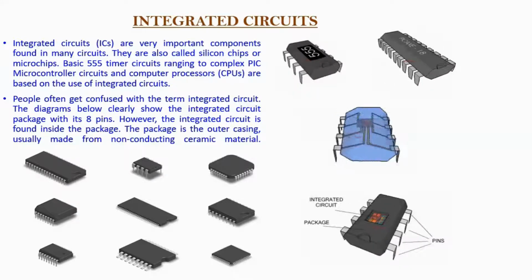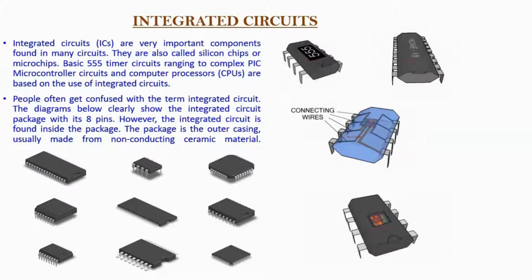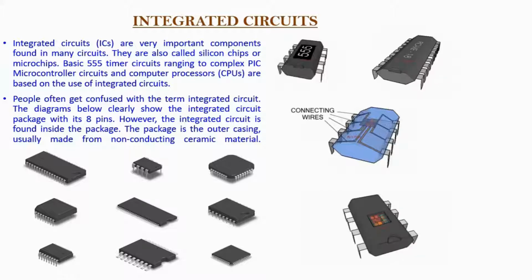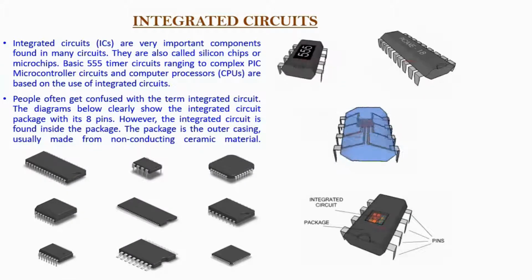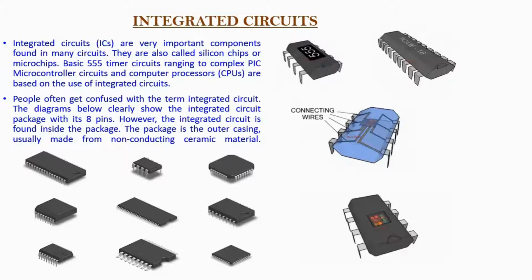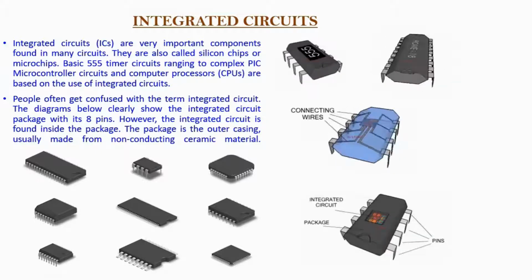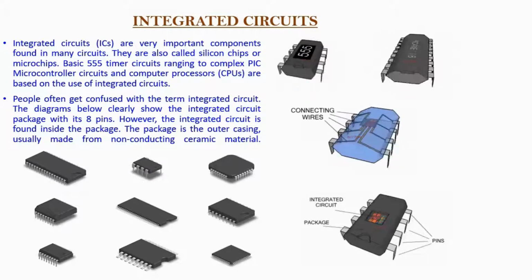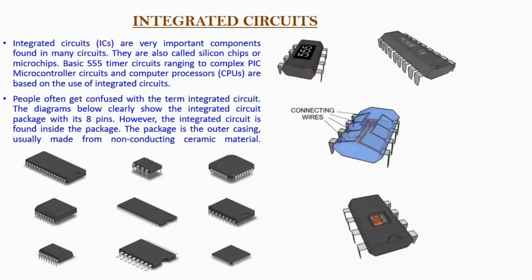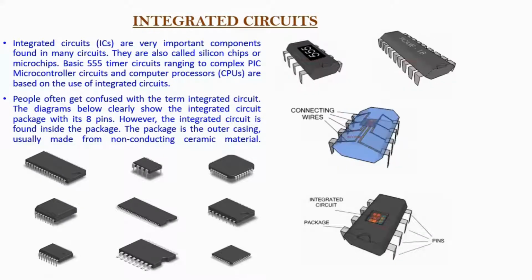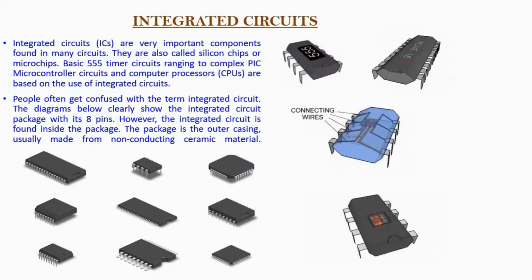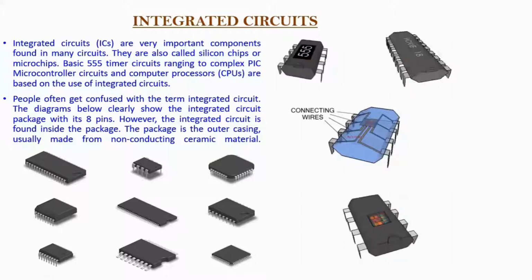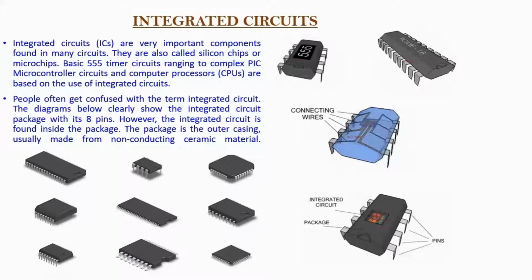You can see 3-pin ICs are mainly, not transistors, but what is called a regulator IC, power regulator, linear power regulator ICs. Okay, so microcontrollers and memory ICs all come under digital ICs. We'll study about that. Okay, so this is about an IC. A little explanation I've given you about IC. It will have a different number of pins. There will be a notch, and on the left hand side of the notch, that is anti-clockwise, you have to count the pins.